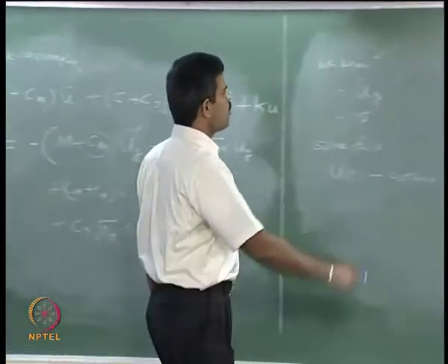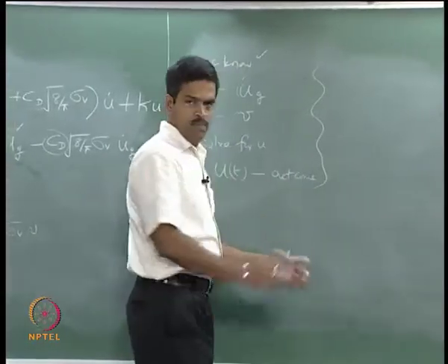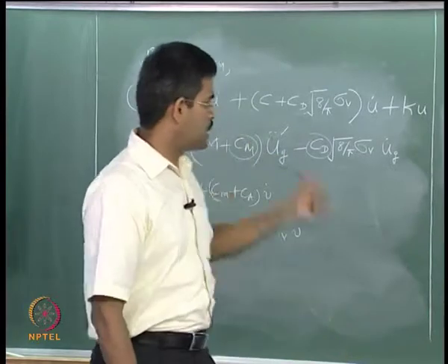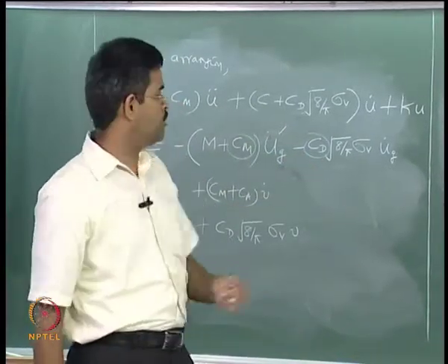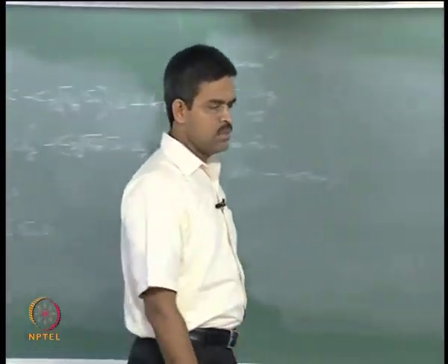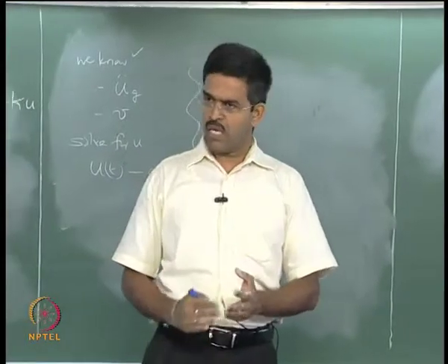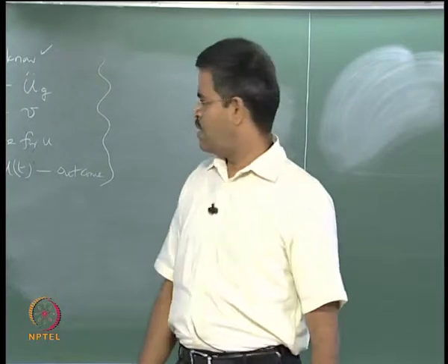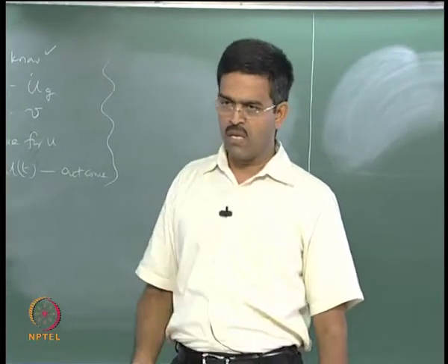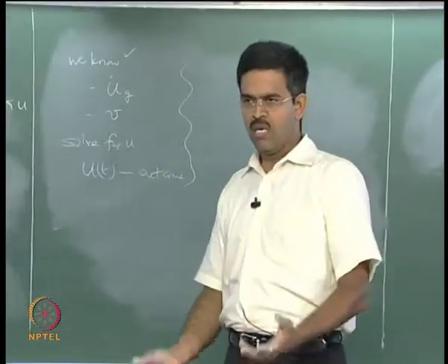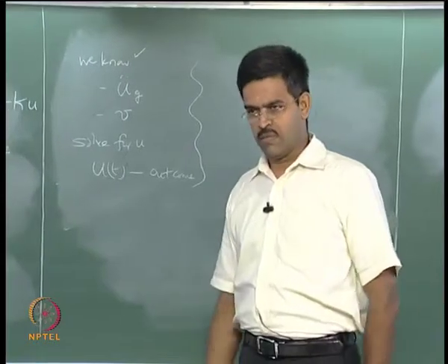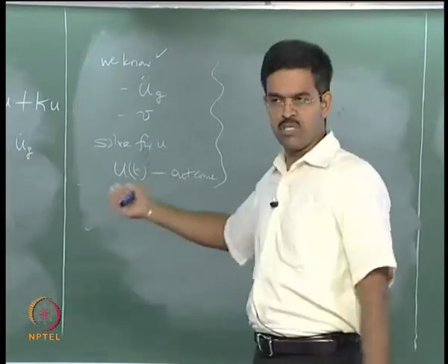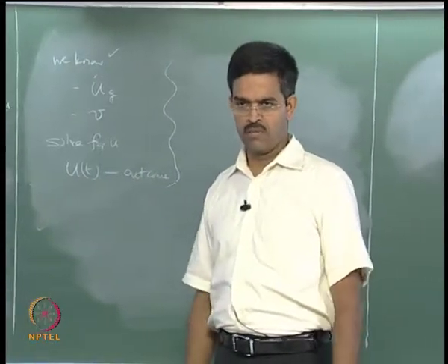How to solve this, and what will be the scheme to solve this in time domain, we will see in the next lecture. We will take up a time iteration scheme advised by Newmark's beta method, and there are many other schemes suggested, Wilson theta method, etc. We will look into those schemes in the next lecture and see which scheme I will apply and how the scheme makes it iterative. We will not solve the problem here; I will show you the results and solutions for this particular case.